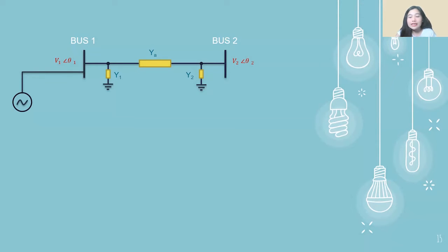Okay, as I've said, our shunt admittances are line charging capacitance. So it will always be there to be considered when there is a presence of shunt admittances and medium length transmission lines. It will vary along the way in different circuits, as we have different constructions of circuits, different types, and different connections.